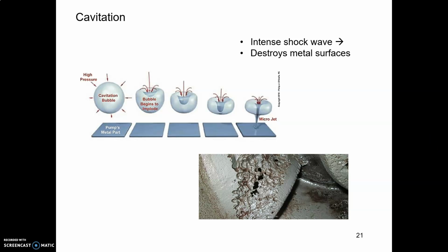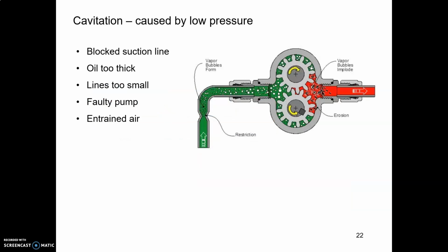And as these bubbles form and explode, they create these intense shock waves, and those shock waves hit the surface of your pump. And here's a picture of a pump that had cavitation, and you can see why cavitation is so noisy. It just chews the heck out of your system. So when you hear that, you know we need to do something.